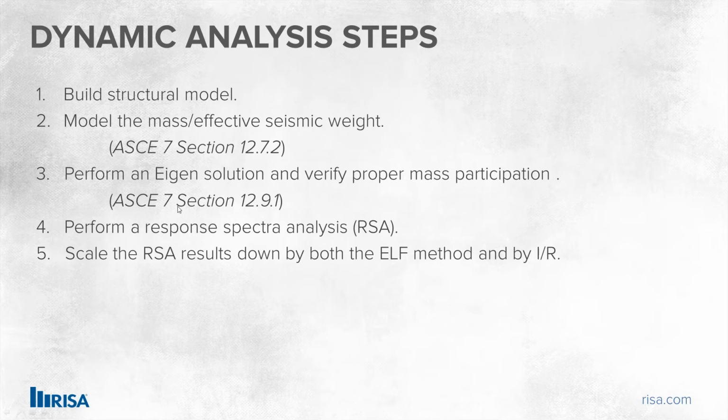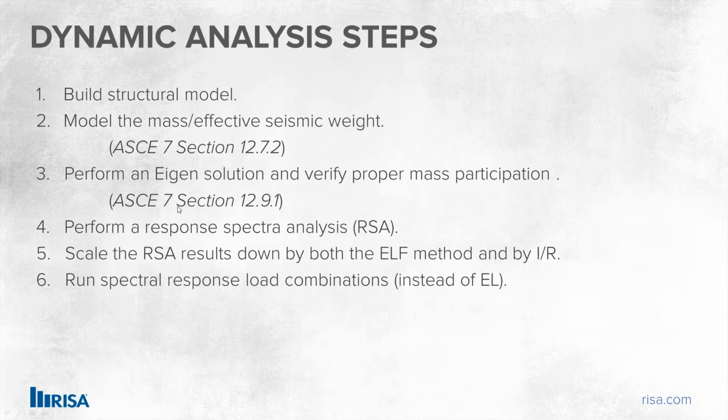And lastly, once you've performed 3 and 4 together, you're going to get the results of that dynamic analysis, and you're going to apply it to the structure. So you're going to scale those forces that you found from your dynamic analysis in 3 and 4 and apply them to the structure, scaling based on the RSA results. You can scale it back. We'll see coming up how you can scale the factors to either be closer to the ELF, the equivalent lateral force method, and you can also adjust it to be inelastic, or we can see here I over R is going to be our inelastic results.